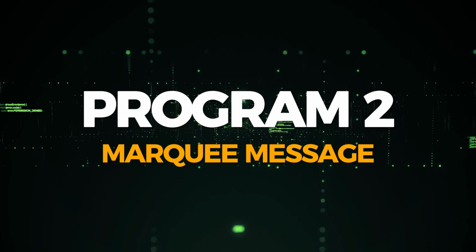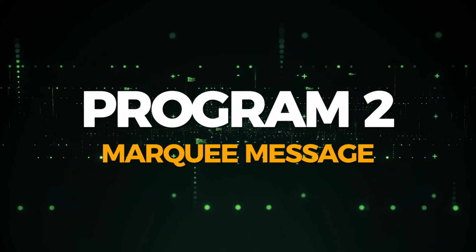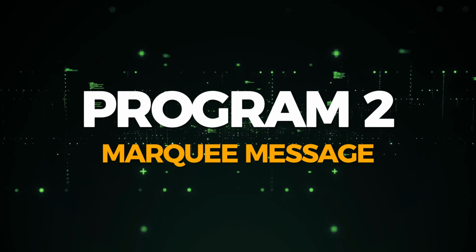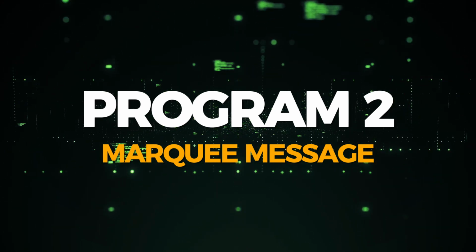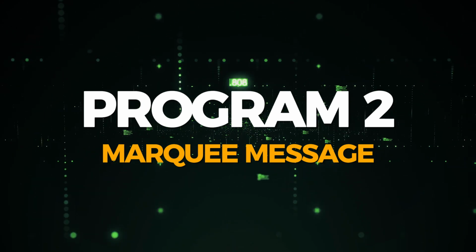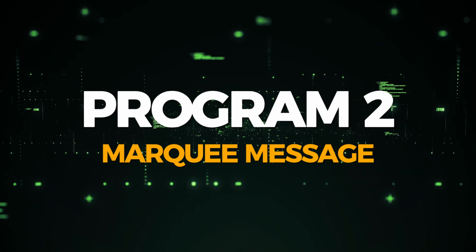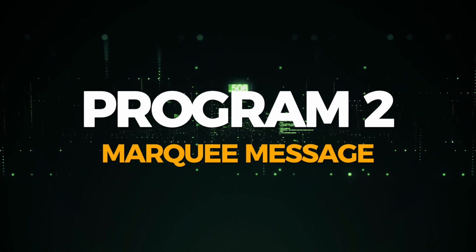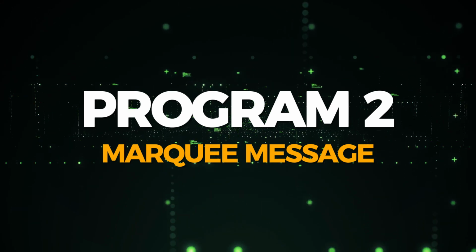Program 2 creates a message marquee system controlled by 2 light-dependent resistors. It displays 2 scrolling messages based on LDR input. If the left LDR detects light, the message "Welcome to the PCPE department" scrolls from left to right. Otherwise, the message "Goodbye, see you again next time" scrolls from left to right.